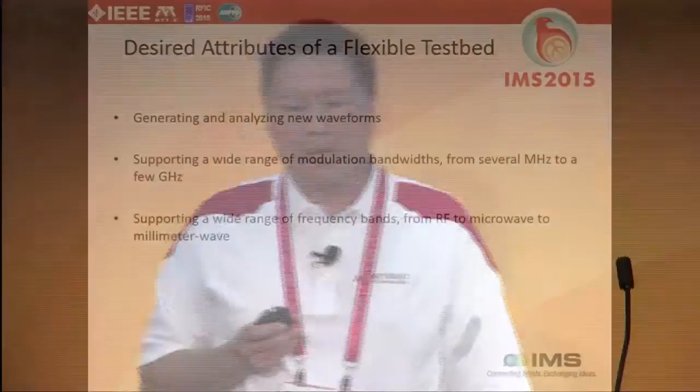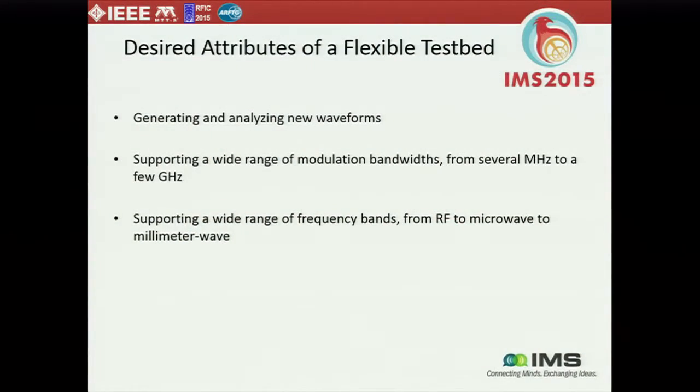5G applications. And so some of the desired test bed attributes include generating and analyzing new waveforms, supporting a wide range of modulation bandwidths from maybe several hundred megahertz to maybe a few gigahertz, supporting a wide range of frequency bands, maybe from RF to microwave to millimeter wave frequencies.